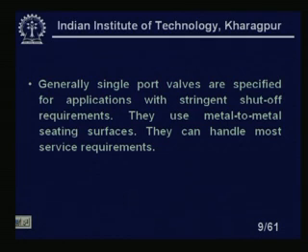Generally, single port valves are specified for applications with stringent shut off requirements, where the shut off has to be very tight. So, I need this type of valve. You may ask why I should then use a butterfly valve. As I told you, the response time of the butterfly valve is very short. That means it takes very quick action, whereas in the case of the sliding stem single port valve, it takes more time. But if you need a very tight shut off, I have to use a single port valve.